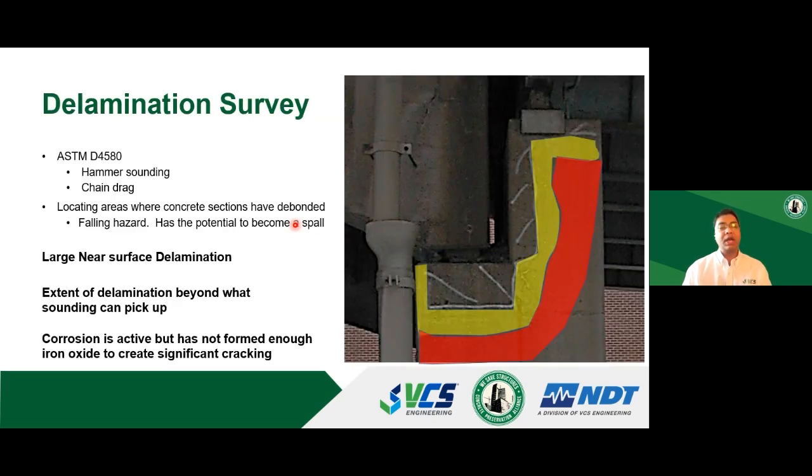We also heavily rely on delamination surveys, hammer sounding surveys, or chain drags. Essentially, when you perform a hammer sounding or a chain drag survey on a concrete element, you tend to hatch out those elements.